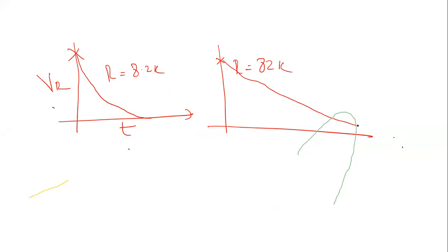So it will take 10 times longer time to reach that 0 volt, like this. Now what is the difference it makes? Now the time duration at which it crosses around 1.5 volt is here, which means the duration for which the circuit remains in reset is this delta t. The circuit remains in reset for this much amount of time here.